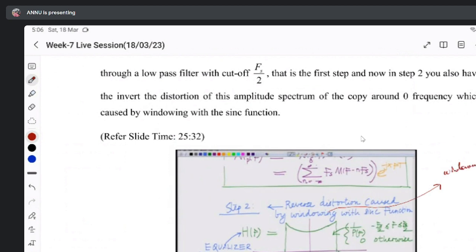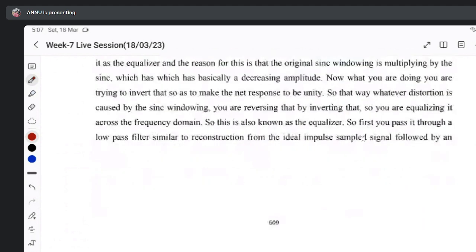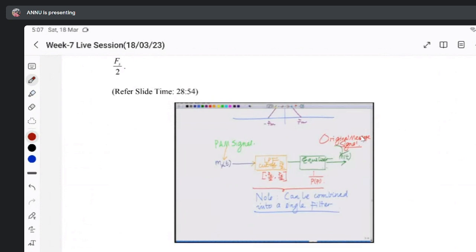I don't recall, ma'am. Butterworth filter, Chebyshev filter, in that also we refer to windowing. In filter design, we will have the filter coefficients. Like when we have a sample and hold circuit, we get the samples at every Ts. Similarly, when we design a filter, we have to get the filter coefficients, and how many filter coefficients are required is defined by the windowing technique. So we have the windowing technique in the filter design as well. It's okay if sir has not covered that too.